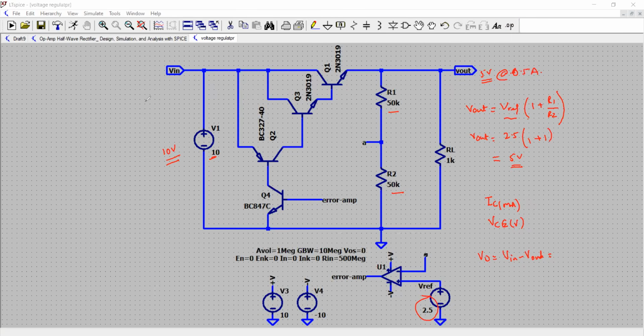You have input current coming from this supply, let's say I. The rest of the circuitry will draw this current supplied by this unregulated source. And this current is then split into the PNP transistor, the emitter of it, the base of it, right here, which is also the collector of this NPN.